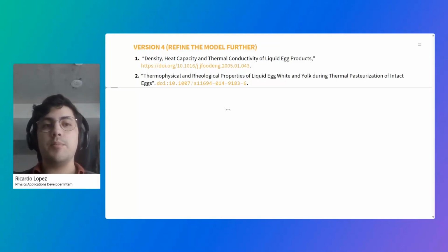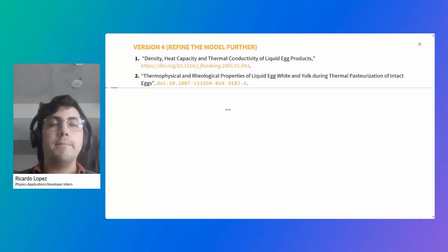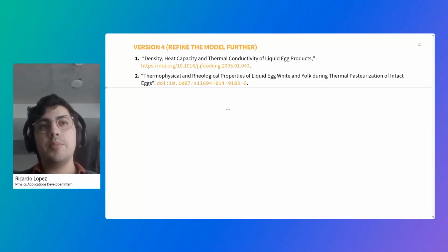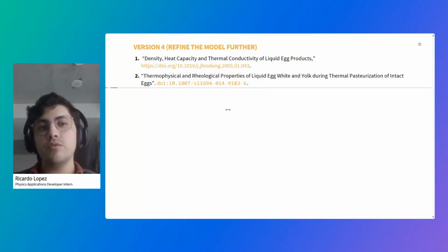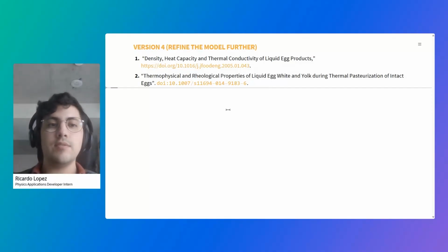These are quantities that might also depend on temperature. So we can now model what happens when we consider the changes in density, heat capacity, and all of that with temperature itself. So it will become a nonlinear model in which the coefficients of our PDE depend on the dependent variable itself.